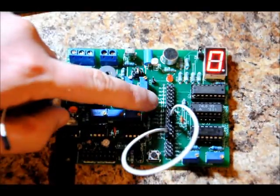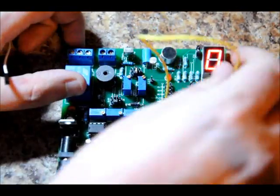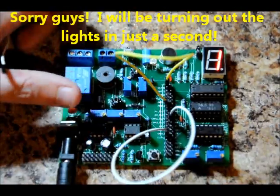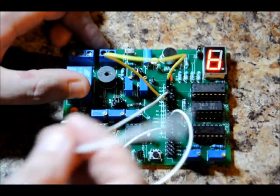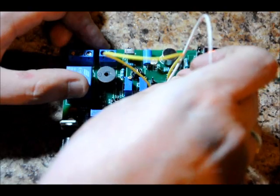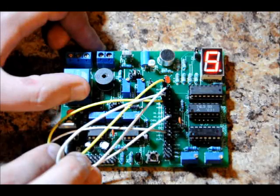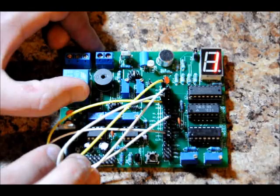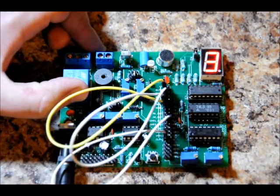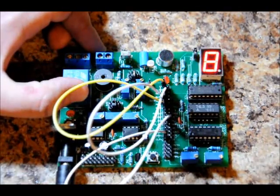So I'm going to connect the AND1 to our out D, which is up at the top. And I'm going to connect my AND2 to my out B. So let's watch this. Let's see what happens. It should reset once it hits 9 or 10, but you won't see 10. See? Now, what happens if I leave one of the lines floating? It's going to continue to count up to 15.